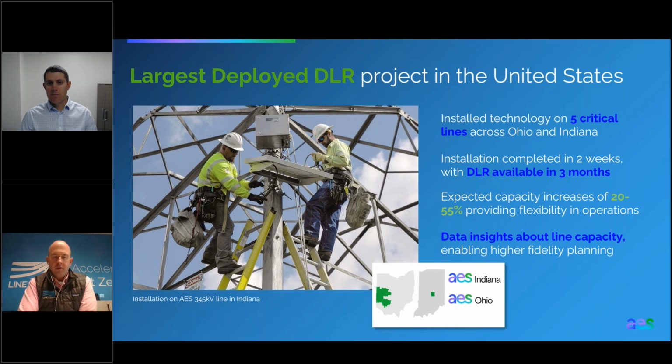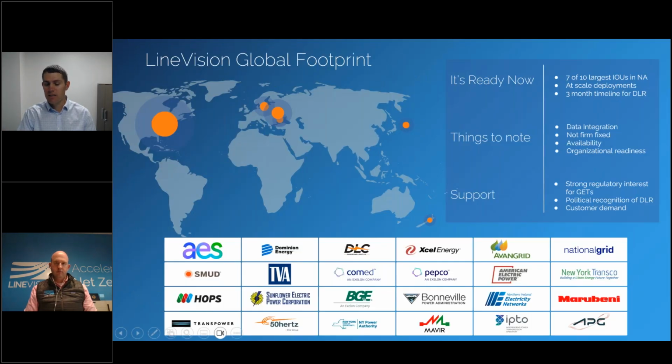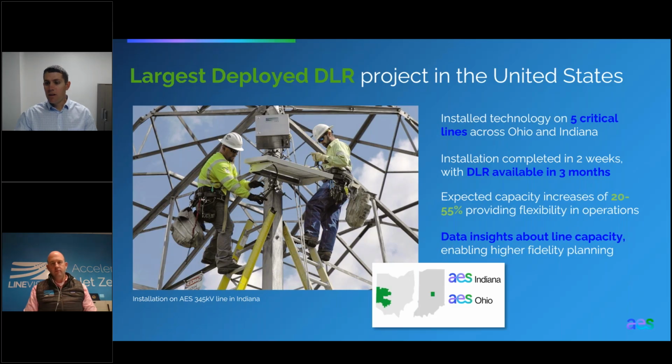So as a concrete example, in Ohio, we have a large Honda battery facility that is located in the southeast part of our service territory that has that 24-month initial startup time frame. The outages needed and capacity needed to facilitate that construction while transmission is being built. We're working on a 345 kV link that will eventually come in 2 to 3 years later. That was a major challenge for us, and we looked to DLR to help solve that challenge.